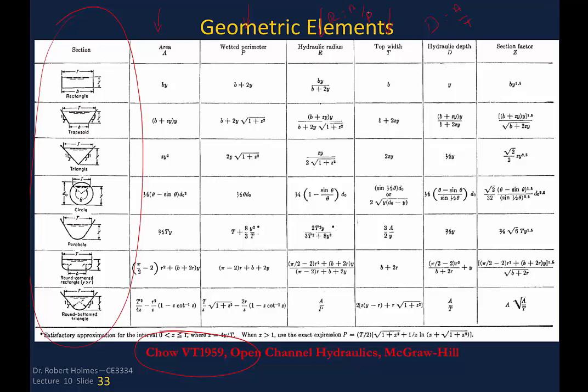And so for a trapezoidal channel, you've got some width here at the bottom, and then you've got these sloped sides, which are going to be characterized by the horizontal to vertical component. So it's 2 to 1 side slopes. That would be z equal to 2, which would mean that it's 2 horizontal to 1 vertical. And that's a little different than how we traditionally think of slope, where we would have the rise over the run. Here we express it as the run to rise ratio.